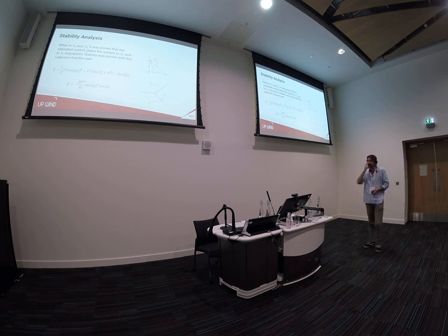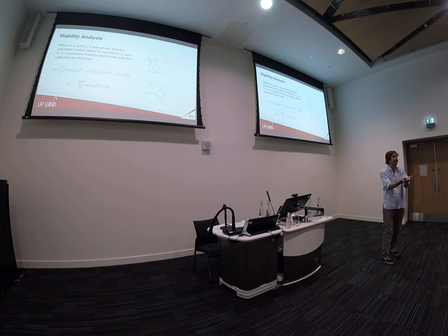Basically, a Lyapunov analysis is the idea is to find an energy-like function that is basically zero when the kite is in the path, for example, for this case, and is always positive everywhere else. Okay, and if the time derivative of that function is always negative, except when in the path, when it is zero.